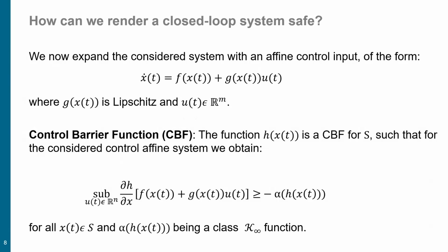And what we just need to make sure is that your system is always in line with this constraint here, right? And this is nothing else but your h dot. So it's the same thing as we had before, but now we have u additionally. And by that, we can obtain, depending on the problem, some constraint on u, right? Either a lower bound or upper bound. But we can just say, okay, if we know our u needs to be something like this, then the system is considered to be safe, right?